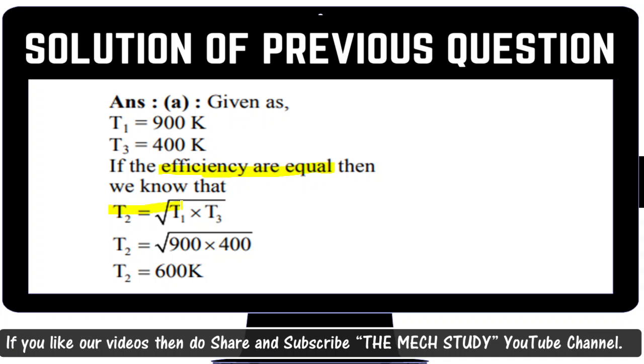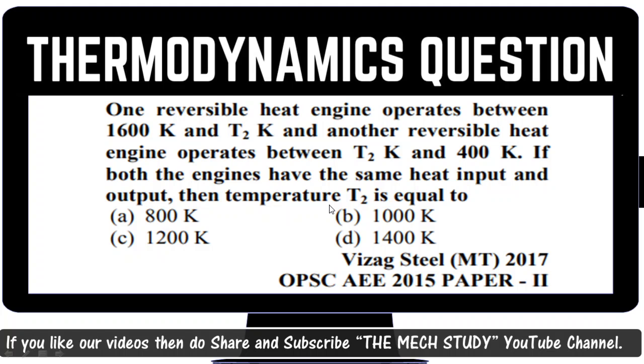So if the efficiencies are equal, then you need to remember T2 equals the square root of T1 into T3. T1 is 900 and T3 is 400. If you put these two values, you will get T2 as 600 Kelvin, as the intermediate temperature of these two engines when the efficiencies are equal. So I hope this question is also clear.